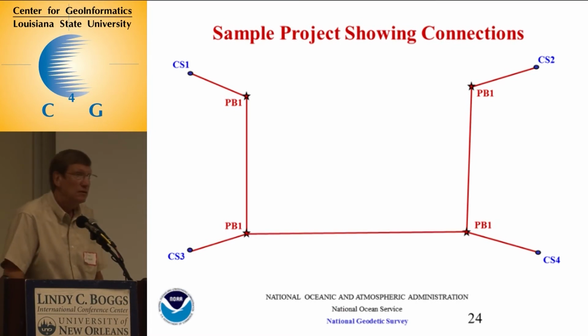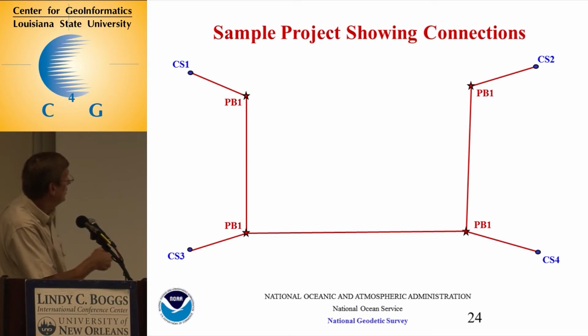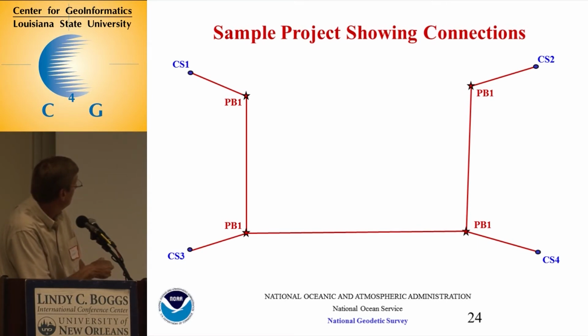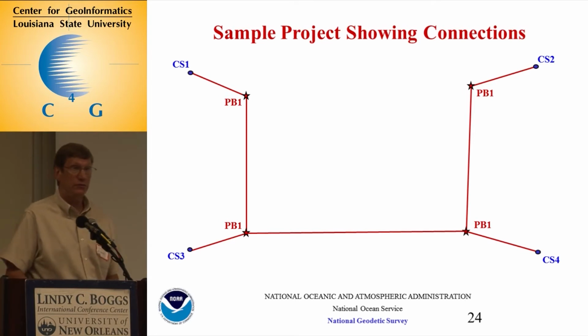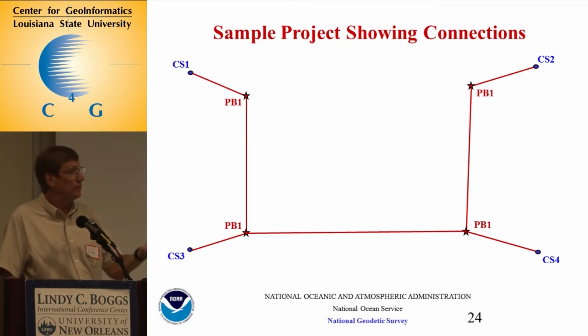And then you connect there. So that gives you your connection from this around to there. That would give you a nice network, because remember, you are trying to make sure that if I have some systematic effect in my observations, I'll be able to see it with these cores. Because the cores I say I know much better than anything else. So if I can't take these observations and get close to what I should get, going from here to here to here, then I know that there's something wrong with my observation.